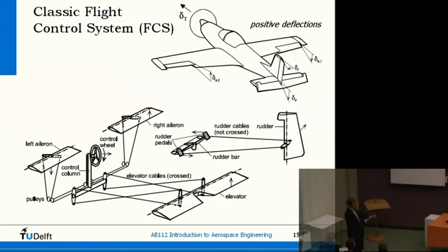But with the yaw, you push on the right side and the airplane does not move in that direction, the airplane moves in the other direction. So that's a historic reason, because of the cables. This was the easiest way to connect them. There were people who thought this was intuitive and people who thought the other thing was intuitive. But if you look at all the controls, it's not fully consistent. The rudder control is also the one that controls the nose wheel, by the way. So these are the basic controls that we use.